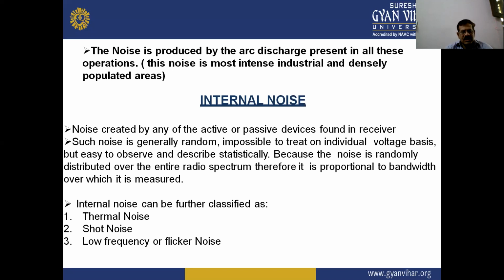Such noise is generally random, impossible to treat on an individual voltage basis, but easy to observe and describe statistically, because the noise is randomly distributed over the entire radio spectrum. Therefore, it is proportional to the bandwidth over which it is measured.